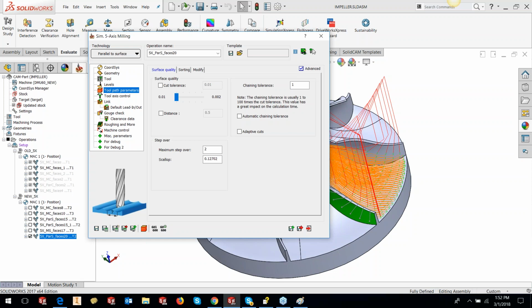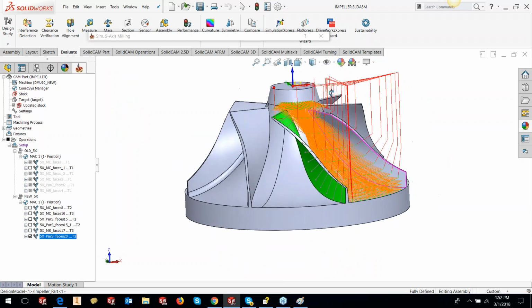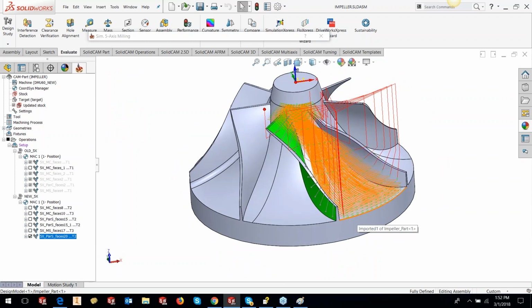That particular channel is a classic example of applying area roughing. So it doesn't actually just say impellers. You can use it on the parts that are displayed on our website also. So you have a nice roughing toolpath here already, similar to what we create with multi-blade.